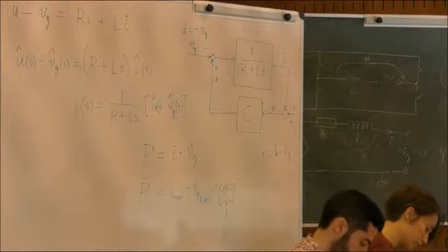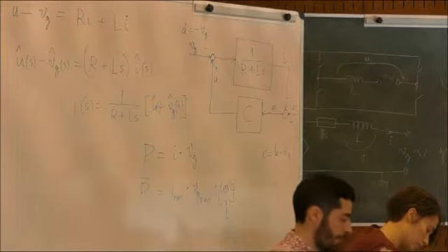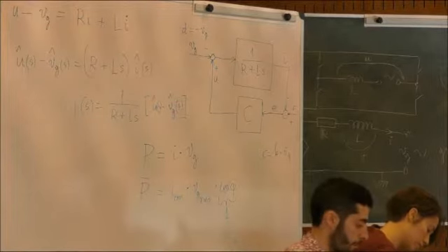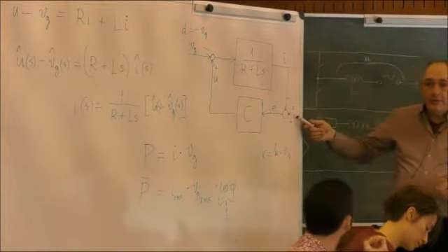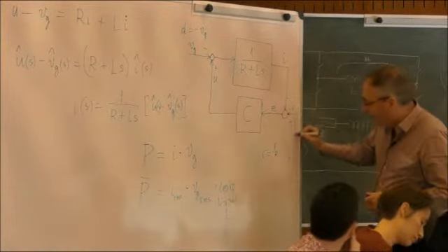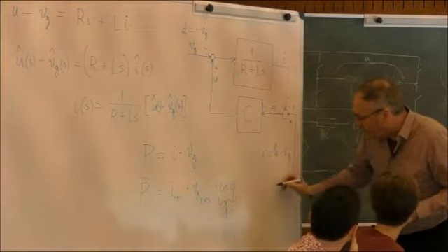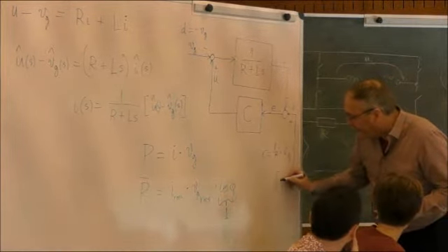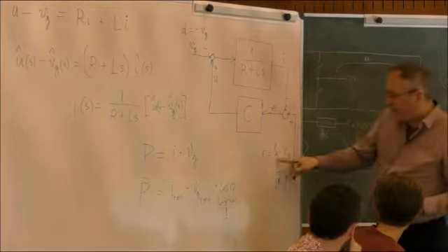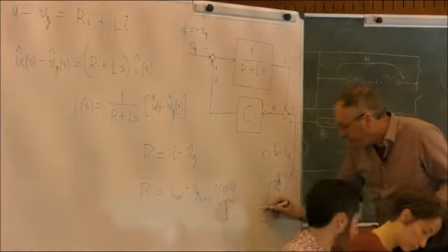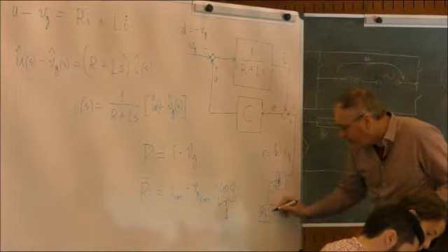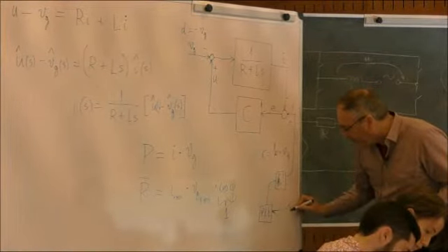Yes, that is the role of a phase-locked loop. In order to obtain this R signal here, this R signal actually comes from a phase-locked loop, and it is multiplied with this k, which is not a constant, I told you. And here is a phase-locked loop, PLL, and this receives as input the grid voltage.